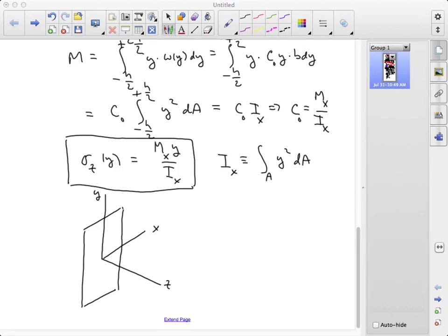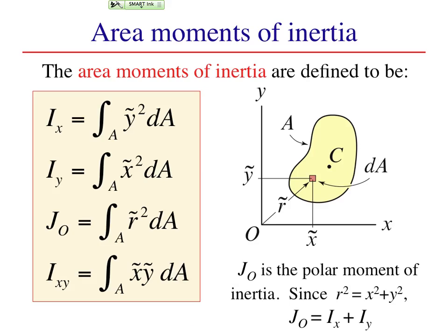This illustration gave us an expression for Ix, the area moment of inertia about the x-axis. But we could define a similar moment, Iy, for resistance to bending about the y-axis, and Iz for resistance offered by adjacent cross-sections to twisting about the z-axis. It's also the case that in this particular illustration, we positioned our coordinate system at the centroid of the cross-section, but that doesn't necessarily have to be the case. Generally, the xyz coordinate system can be positioned anywhere relative to the centroid of the cross-section.